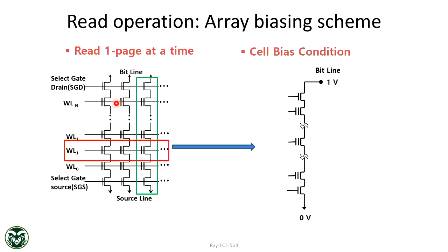So in other words, if you look here, this is the selected word line. You put a reference voltage, which will be low, say 1 volt, but you put high voltage on the others. Pass voltage will be more than the highest threshold voltage in the array. Suppose your highest threshold voltage is 4 volt, right? So pass voltage has to be at least 4.5 or 5 volt, so that whether it is erase or program, doesn't matter, it conducts on all the unselected word lines. Only the selected word line will decide whether current will pass or not. That's how we read the particular selected word line.